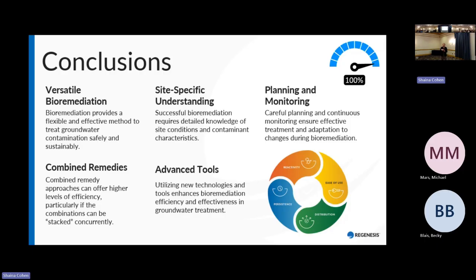What I always love to do, if possible, is if you're doing some sort of targeted excavation, but you know there's almost certainly some residual mass there, add in some sort of amendment while you have an open excavation, whether that's a chemical oxidant, some sort of bioremediation agent, or activated carbon, whatever the case may be. When you have open and free access to an area that you know is contaminated, that's always a great opportunity to add in one of these reagents. And then you know that the contact at least is there, and you're keeping that variable out of the equation.